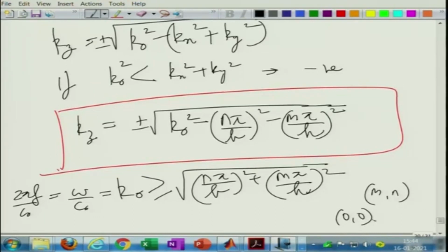Now, depending upon the geometry, typically we consider b equal to h, that is a waveguide with a square cross section, so that things become easier to analyze, although it need not be square. Then we can figure out what is the first mode to get started or to be propagated. So, now we have this kind of solution, or the expression for the cut-on frequency.